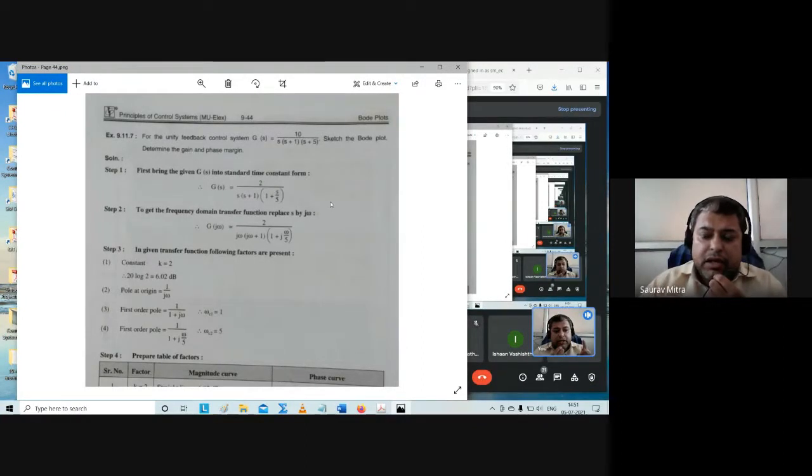In all the numericals we have seen so far, every time in the denominator I gave you two single poles, and in one case I gave you three single poles, but with that I added one single zero. That means every time the maximum phase could go to minus 180 degrees. So we never saw what is called omega PC.